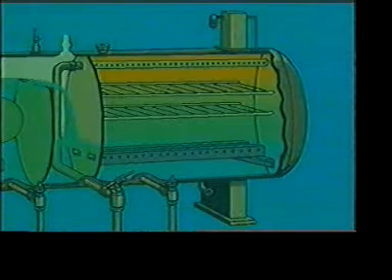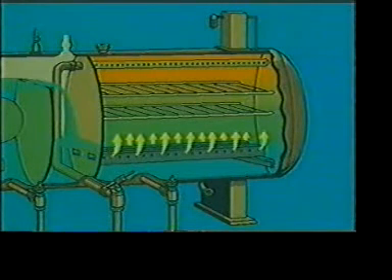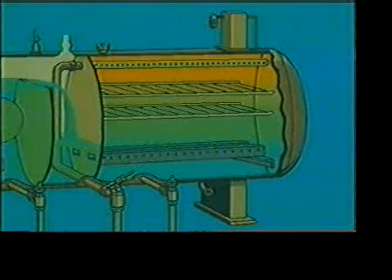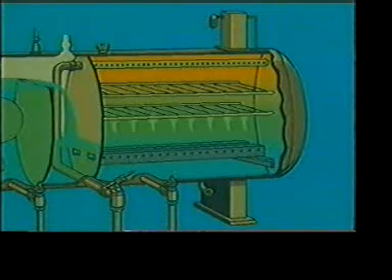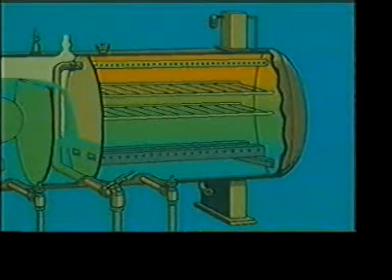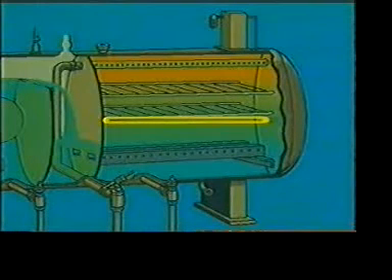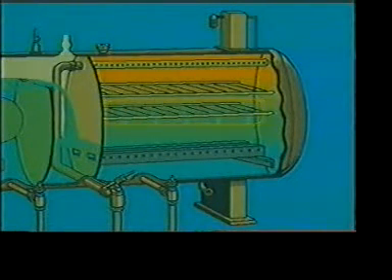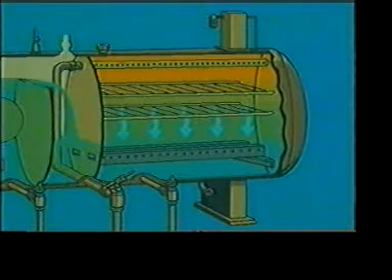Finally, the emulsion reaches the treating section. Here, flow spreaders ensure an even distribution of emulsion throughout the treating section. From the spreader, the emulsion rises upward towards the high voltage alternating current electrical grids. Electrostatic treating begins below the lower grid and is completed between the upper and lower grids, where the water droplets combine or coalesce and settle out.